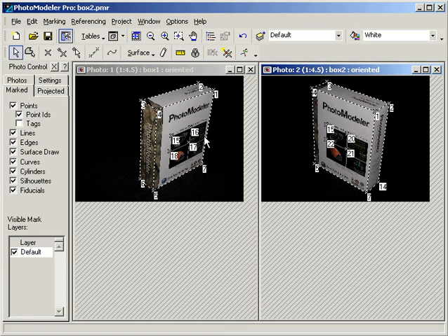We select Shift and use Quick Reference to finish matching the points. Quick Reference is useful when doing a small number of points, while referencing mode is more appropriate for referencing many points. Next, we will use the Line tool to connect the 4 points.